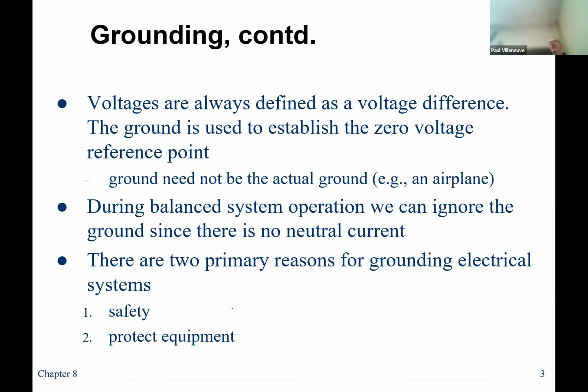When you're talking about transmission or distribution, transmission typically runs almost perfectly balanced. You get as close as you can. In distribution circuits, it almost never is. It's too difficult to make it. But we're focusing more on the transmission system. I had a student who's taking this class online stop by and take a look at a book on how to actually analyze unbalanced distribution systems, and it's a lot more work. So that tends to be a graduate level course. But for an undergraduate level course, we can assume that the systems are fairly well balanced.